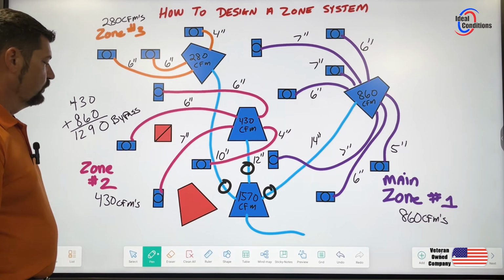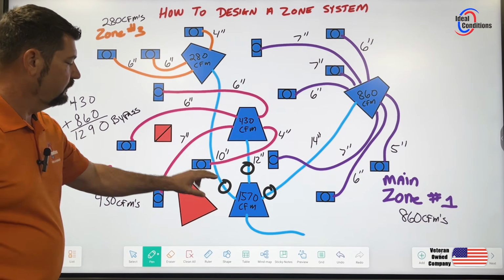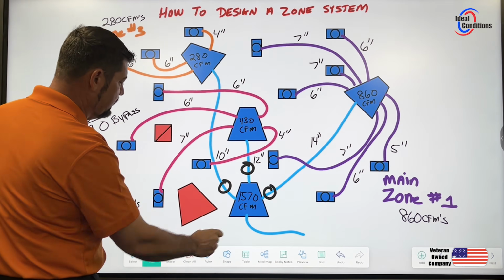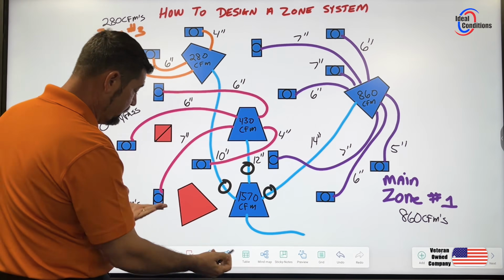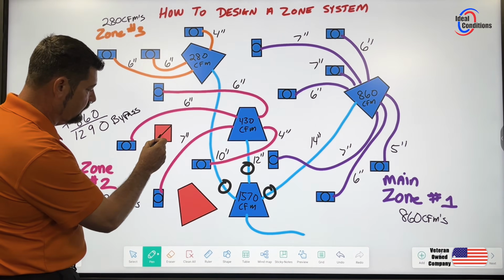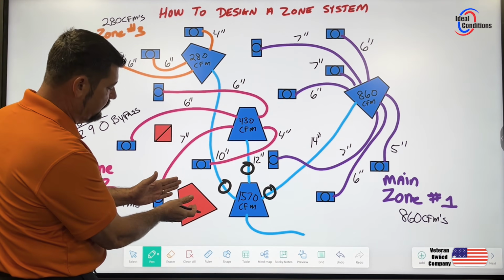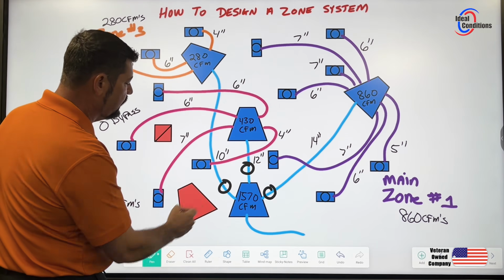And so we would put an additional mixing box right here, just like I cut this in. I spliced that in. I would go ahead, because typically you would just have this trunk line coming off of this 18 going right to the unit. We have a mixing box that's doing that. It offers a side, which is great.